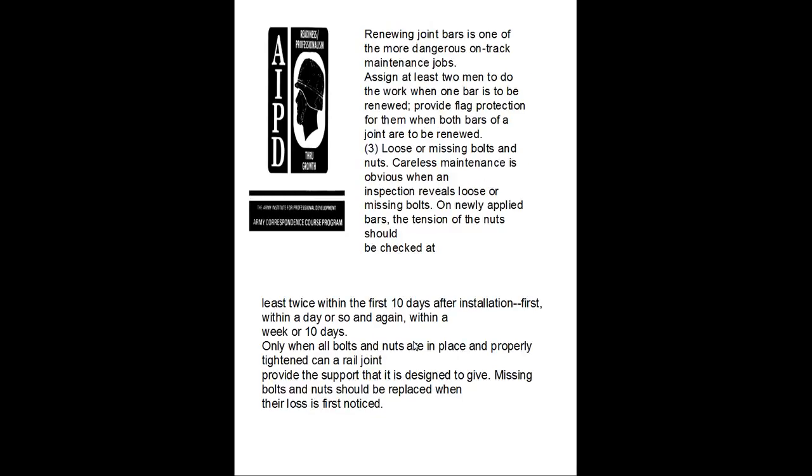Renewing a joint bar is one of the more dangerous on-the-track maintenance jobs. Assign at least two men to do the work when one bar is to be renewed, providing flat protection when both bars of a joint are to be renewed.